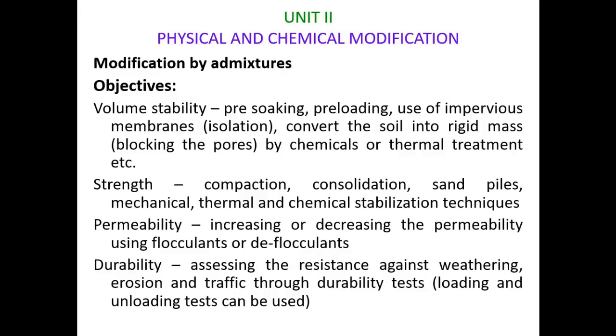Inadequate pore pressure dissipation causes slip failures in earthworks. High seepage pressure causes tunneling, and low permeability of subgrade soil causes failure of roads and pavements. In regions of intermittent rainfall, a perched water table can form above the impermeable clay layer, which causes trouble during construction.